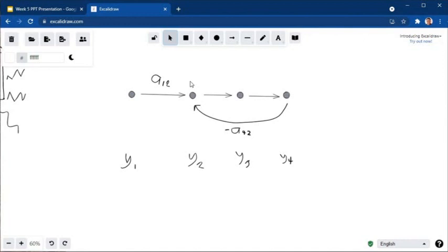When it measures the temperature as still greater than 18, it will continue to produce cold air. When it starts to measure 17 degrees Celsius, the output is now not as intended. The intended output is 18. When it measures, let's say, 17 or 16 degrees Celsius, it goes back to the system and says, hey, this is not equal to 18. What should we do? It will stop producing cold air.